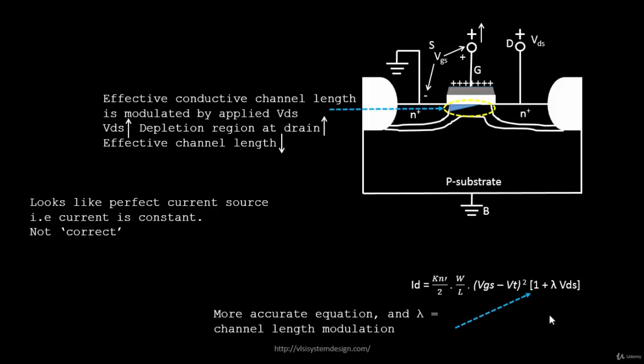We'll take this complete equation and multiply it by 1 plus lambda VDS, and we'll try to prove this in a separate set of videos where we'll be looking only into physics equations. Let's keep this for now, but we'll add this term to the drain current equation, showing that it's not completely independent of VDS. Whenever you increase your VDS, you still tend to see some behavioral changes. So drain current is not constant, but slightly increases when you increase your VDS, and we'll show that when we do the SPICE simulation. Now this particular equation becomes your constant current equation for the saturation region of the MOSFET.